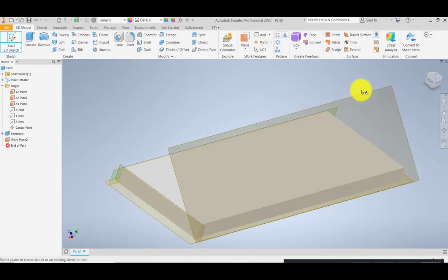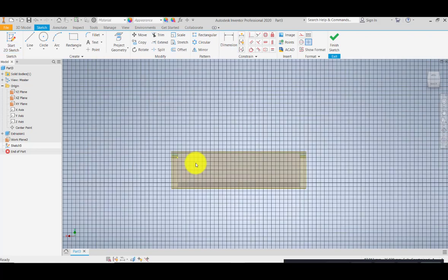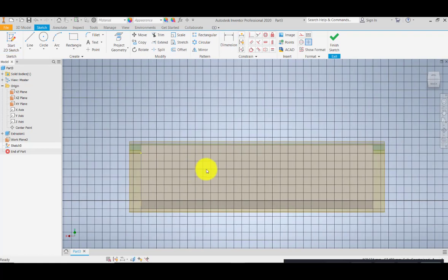So I will be drawing the sketch on this surface. In order for us to have a constraint, for example, we want this new extruded part feature that is being created not to overlap the base geometry. And also, to make it constrained so that it is purely dependent on these surfaces or on this part feature, what I'm going to do is make a geometry projection.